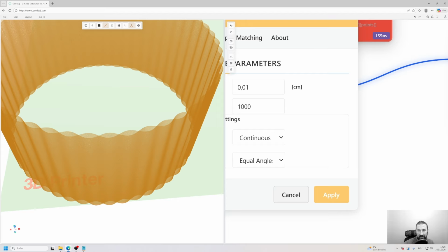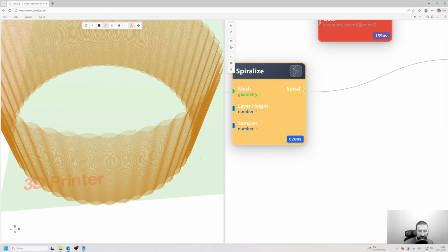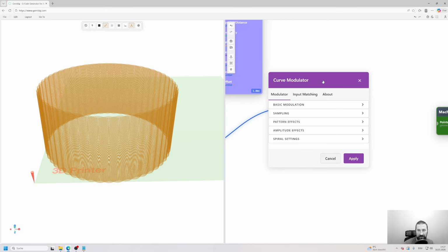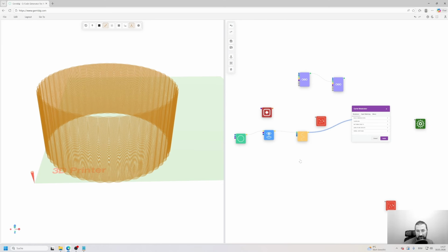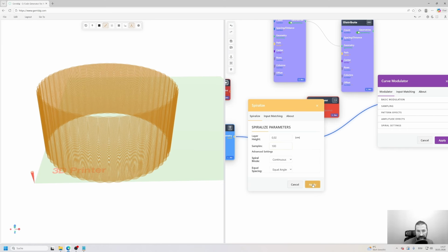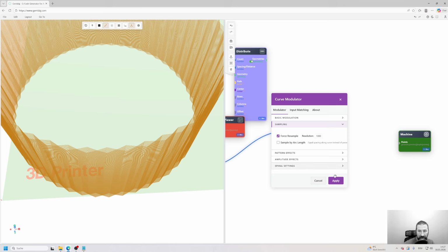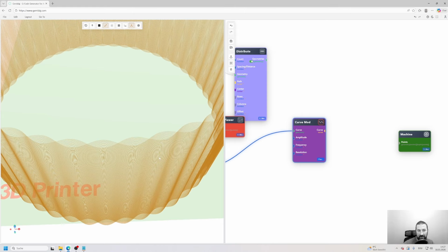You can do it. It's actually not that painful, but normally you can set it to a reasonable value here, so it's much faster, less than 1 second in this case, and then you can still do some resampling in the curve mode. This is extra for this use case. Let's go to 100 back. So you see it's a triangle. It does not have enough points in the spiral, but if you do resampling here, then it's much faster and it still creates a smooth curve. This is done in order to make your workflow more efficient, so your parametric design works much faster than it otherwise would.